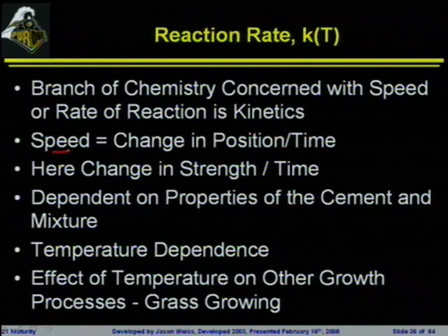So normally if I asked you to define speed, you'd say change in position versus time. Here we're really looking at the change in reaction that's taking place over time, and what engineers are typically worried about is not necessarily how much of the chemical reaction has proceeded, but how much strength we have gained over that last period of time. All right? The theory here is that the extent of reaction can be directly related to strength. Now that is a huge caveat in my opinion, because this is not always the case. And I've made several cases, or tried to make several cases, that it's more complicated in describing concrete materials. We're typically talking about the cement that's reacting.